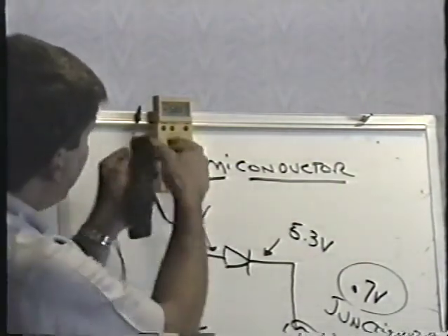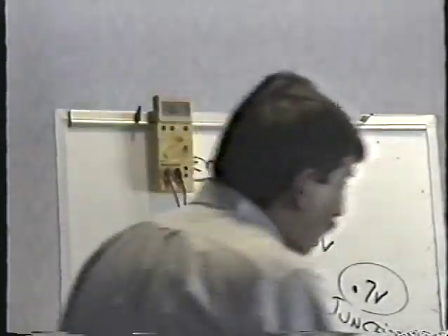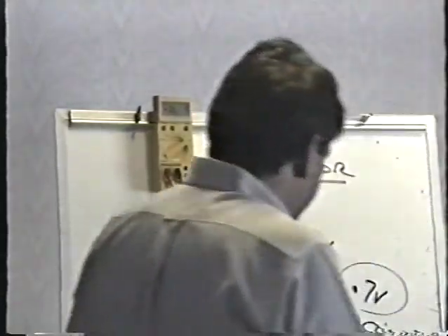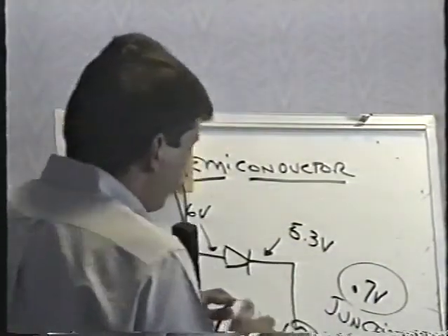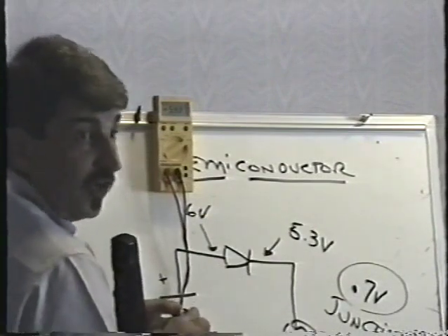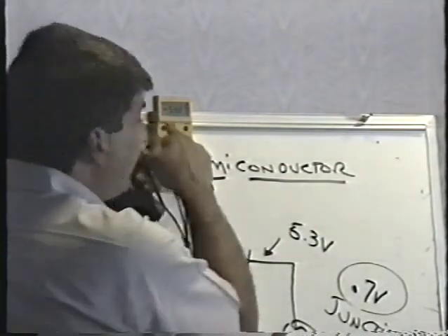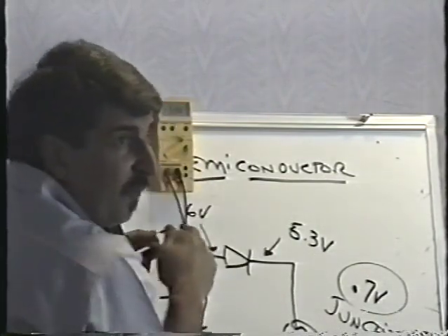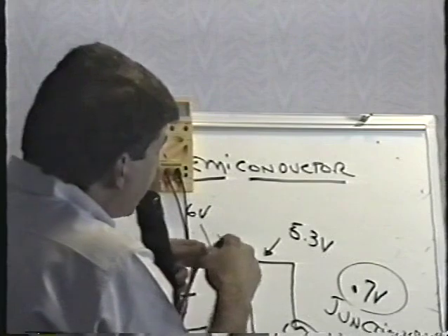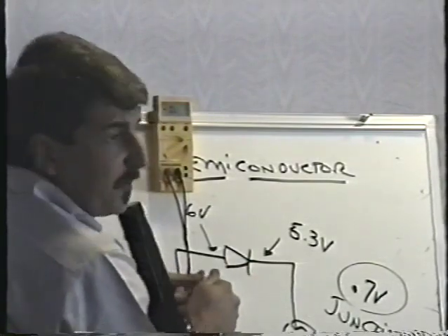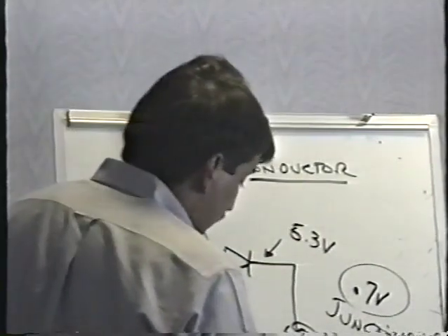Now, here's the little teeny diode. It says 0.584. If I go to the larger diode, it should show me something somewhat lower. It says 0.53. The larger it is, the lower that will be. Even if this read 0.49 or 0.48 or even 0.45, as long as it reads open when I reverse the leads, it is good. Right? Everybody try testing your diodes right now.